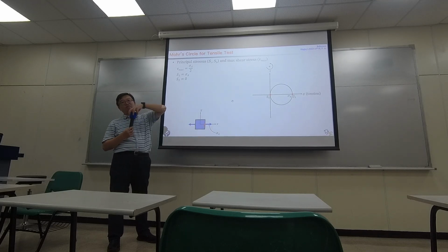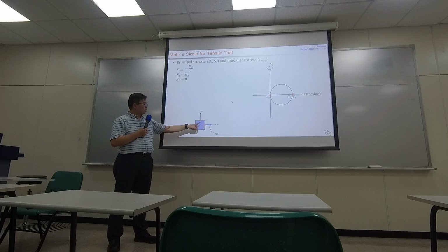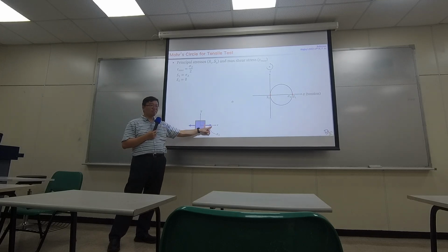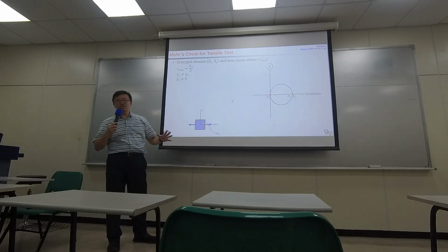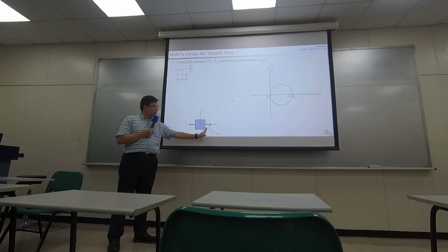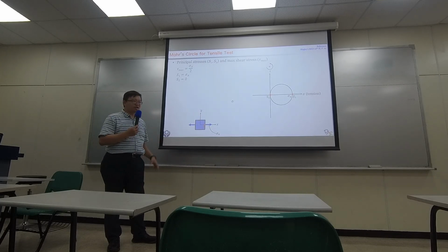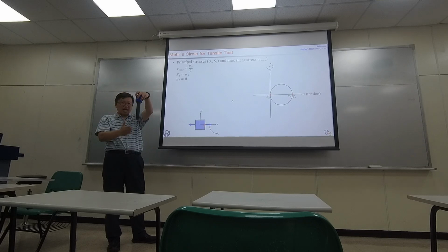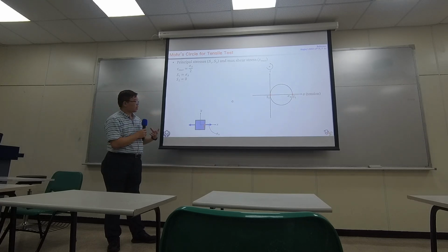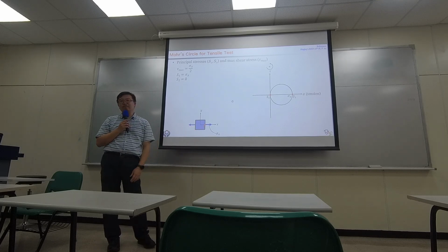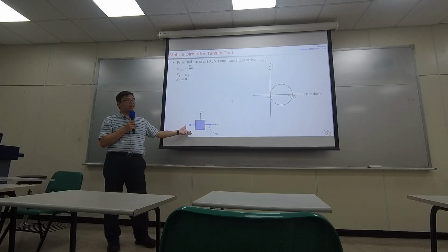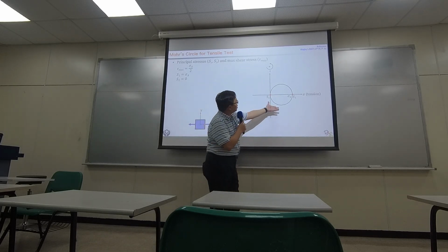And when you start to pull the element, these amounts start to increase, but nothing else. There's no shear along this direction. There's no normal stress horizontally. If this is X and this is Y, there's no stress along Y. So basically, this is a load condition for the tensile test. And if you make a Mohr circle, it's going to look like this.